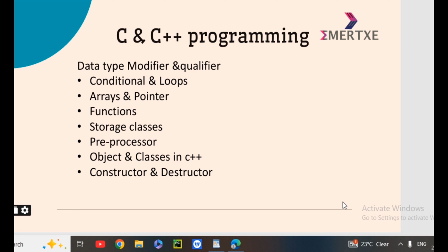Our C and C++ code connects Arduino to the Blynk IoT app via Wi-Fi. It sends sensor data like temperature, water level, and light intensity to the cloud, and also receives commands such as turning the light on or off from the mobile widget.